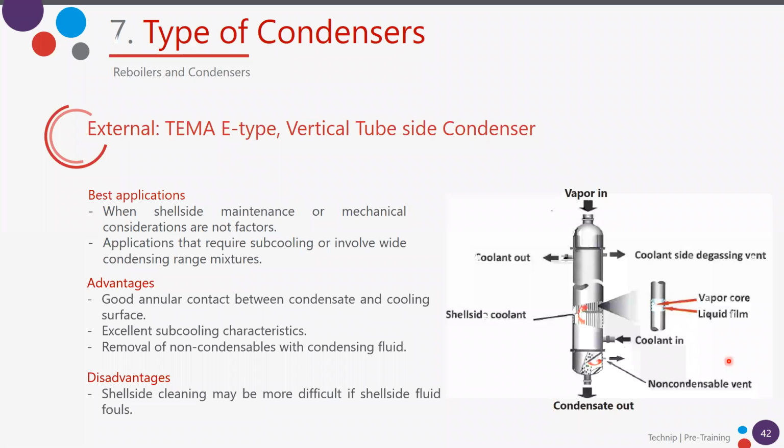So we need to take them out, otherwise they will remain inside the heat exchanger. And having non-condensables in the heat exchanger is not good for the thermal performance because it decreases the heat transfer coefficient. So it's very important we take them out to ensure good function of the exchanger.